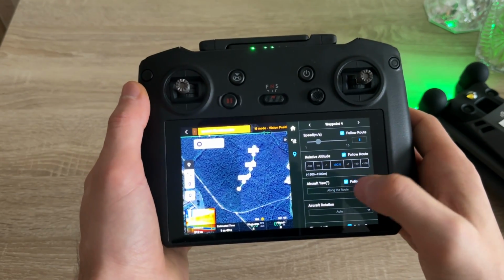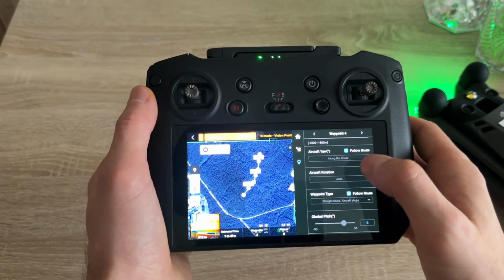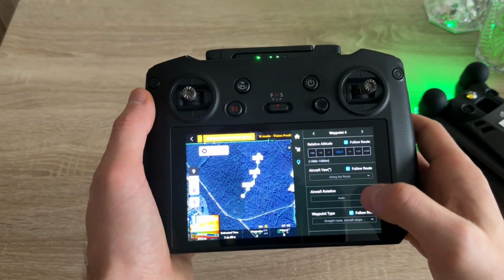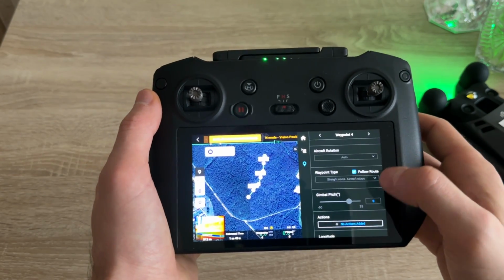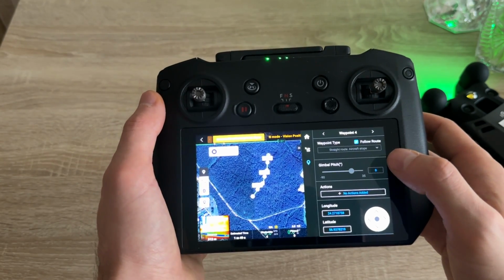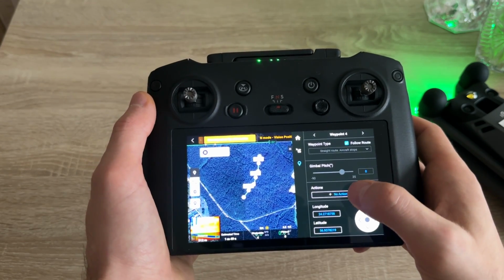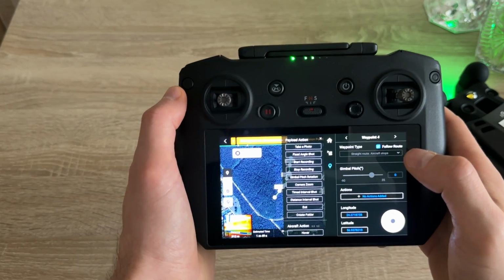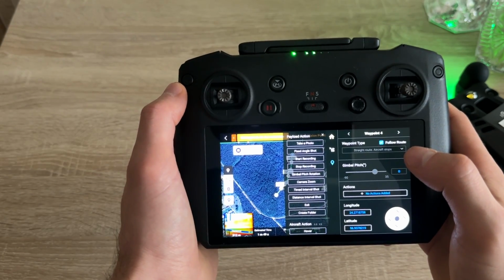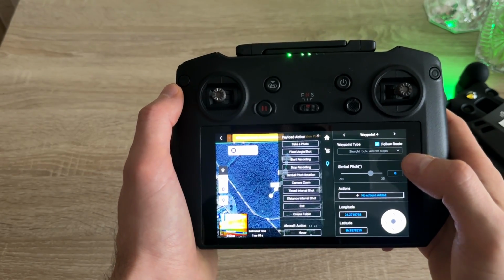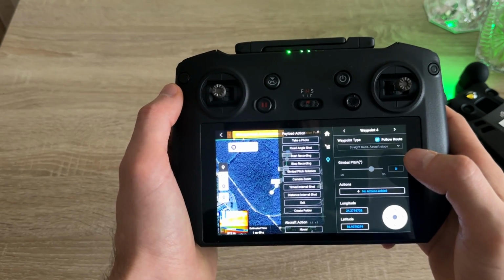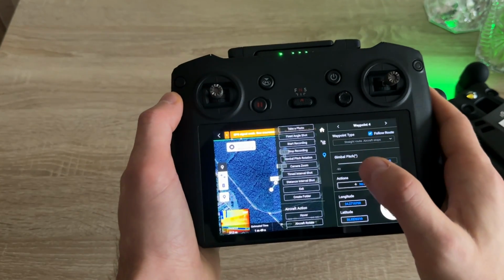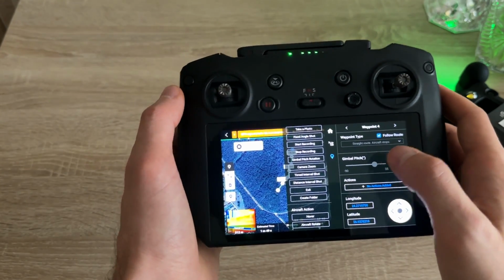And there you can set manually for your waypoints: speed, altitude, yaw rotation, waypoint type, gimbal angle, and other actions such as take a photo, fixed angle shot, start recording, stop recording, gimbal pitch rotation, camera zoom, timed interval shot, distance interval shot, exit or create a folder, and aircraft action to hover or rotate.